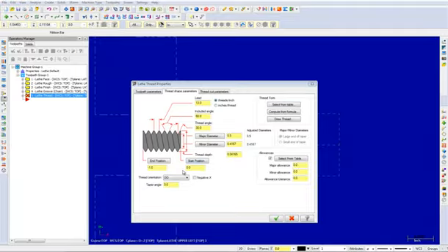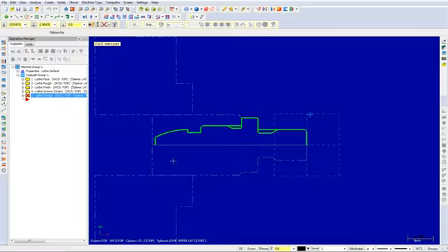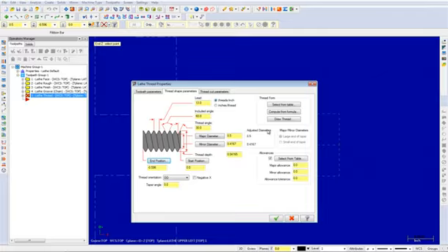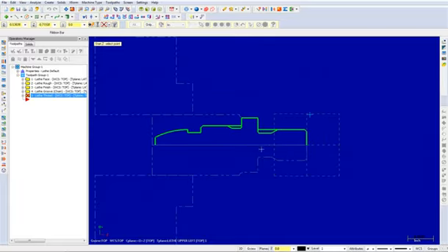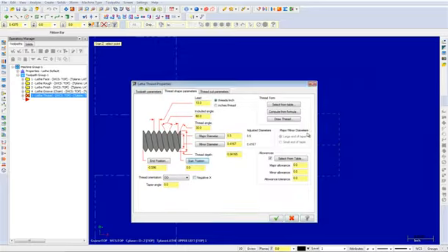From here, select the End Position button and pick the midpoint as shown. Now you should see an end position value of -0.596. Now select the Start Position button and pick the line as shown. Now you should see a start position of 0.